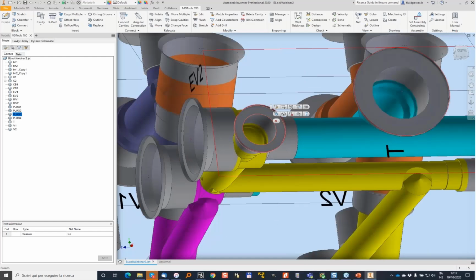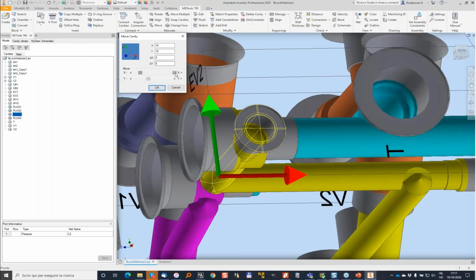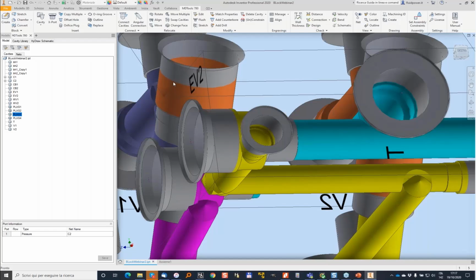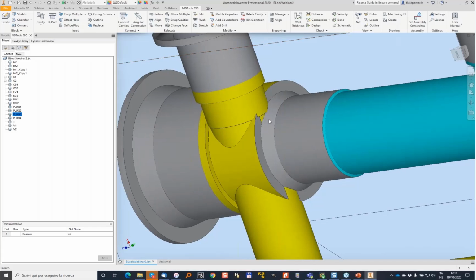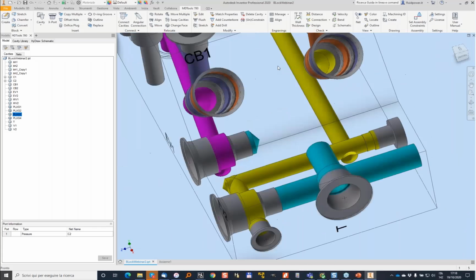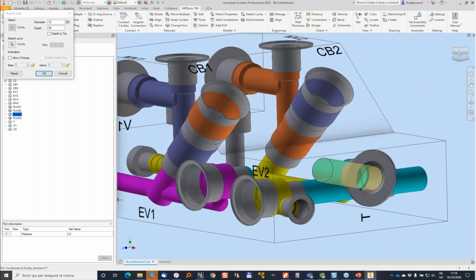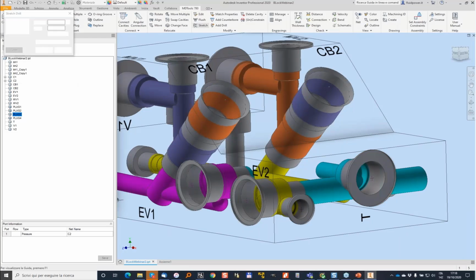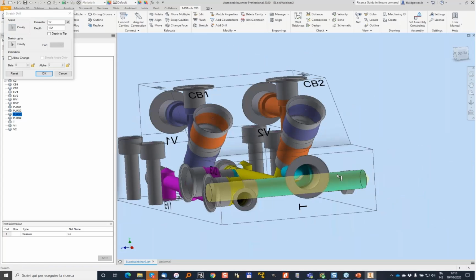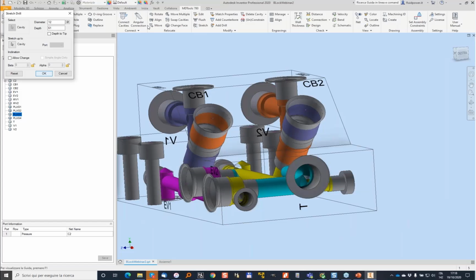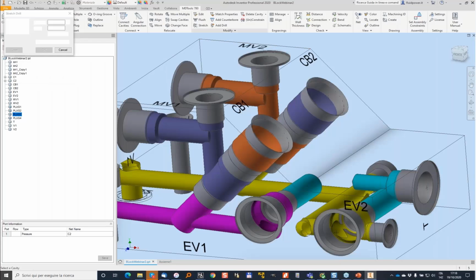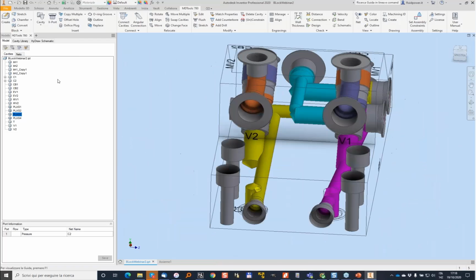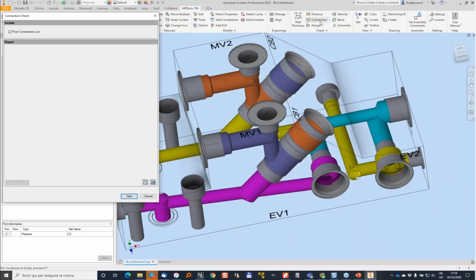And I also can move my drill slightly to the right. Looks okay, although here we have a bit of damage of the chamfer, but let's keep it this way for a moment. Let me make this drill slightly smaller, 8 mm. I also don't need this drill so long. And let me also stretch and go to connect with tank line. Looks good. Let's do a connection check again.